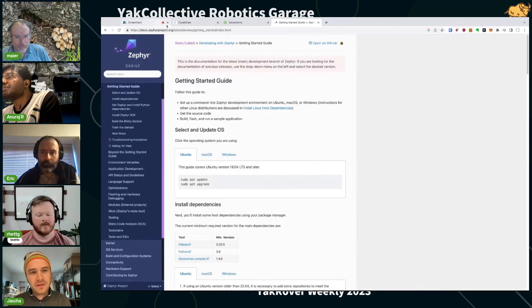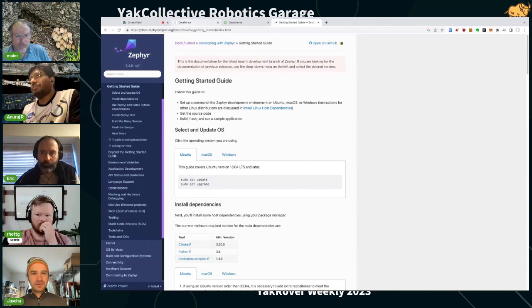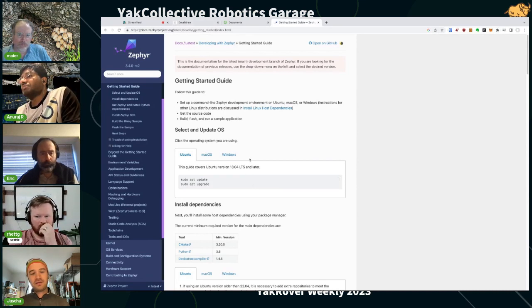Yeah, that's what I'm getting at. If we want to use the ESP IDF, that's very mature, and that's very nice. The downside of the ESP IDF is that it is heavily tied to the specific chip. If we were to use Zephyr, there's a lot more flexibility to move hosts down the road.